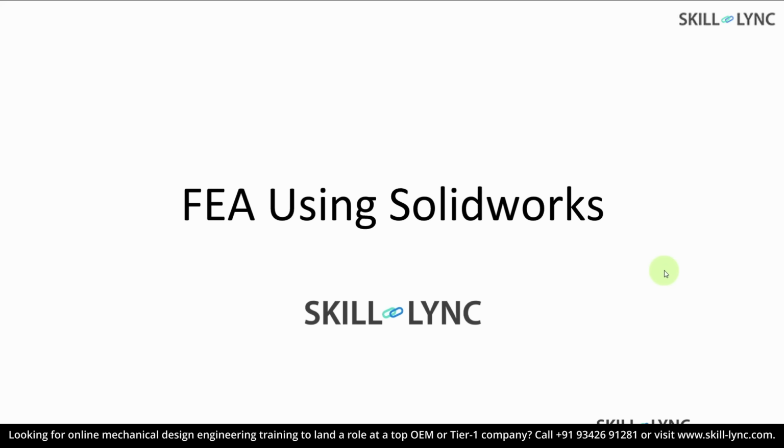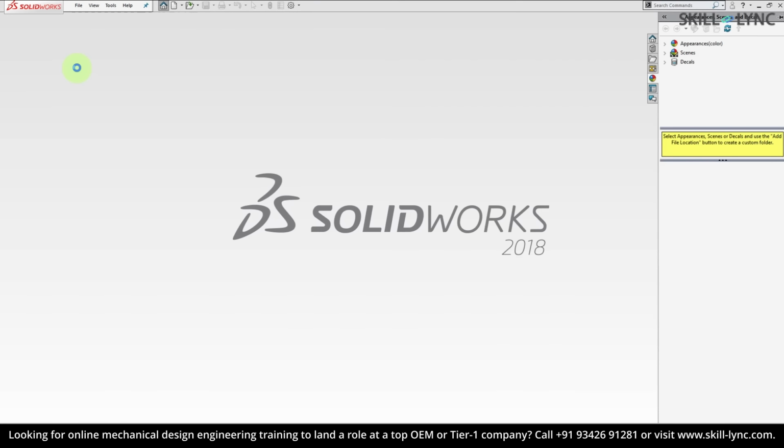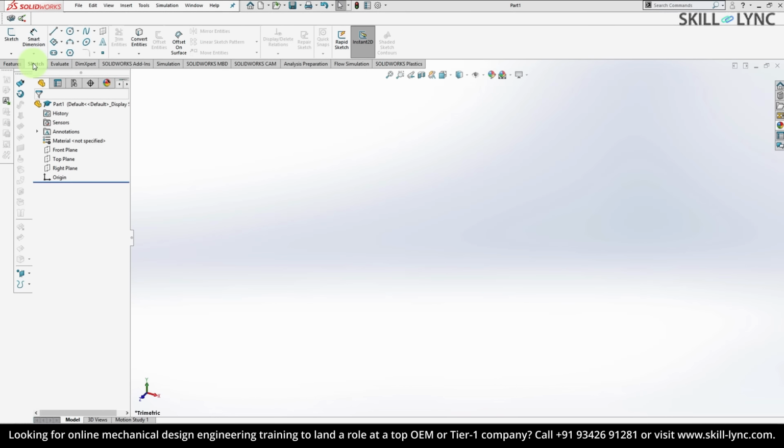Hey everyone, welcome to a new video. So in this video, we'll be learning how to perform a finite element analysis on a uniformly loaded cantilever beam using SolidWorks. So to begin with, let's open SolidWorks, click on the part modeling and click on the sketch module here. Select the sketch, choose the front plane and draw a rectangle.